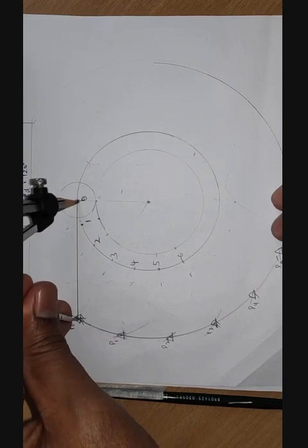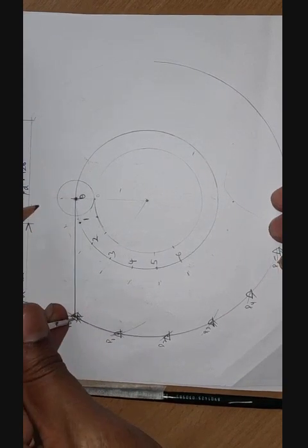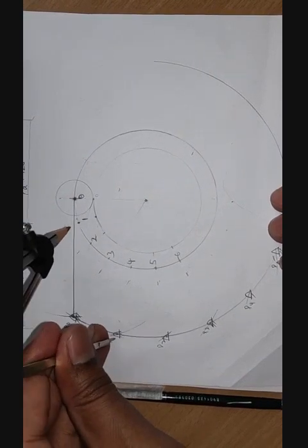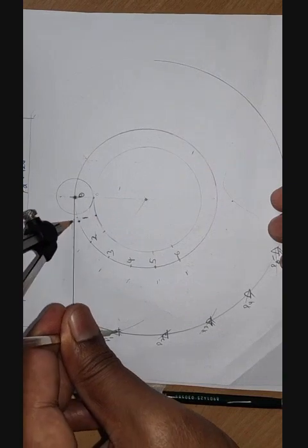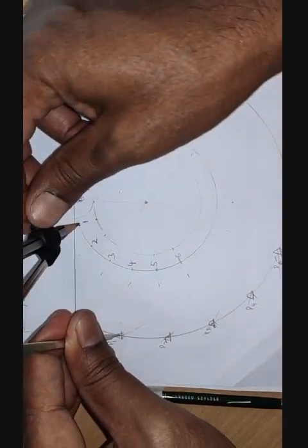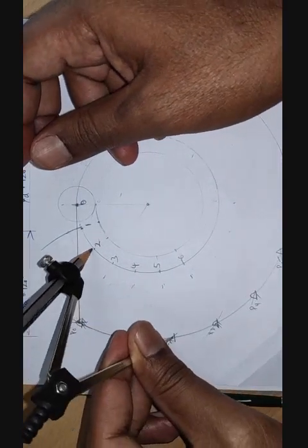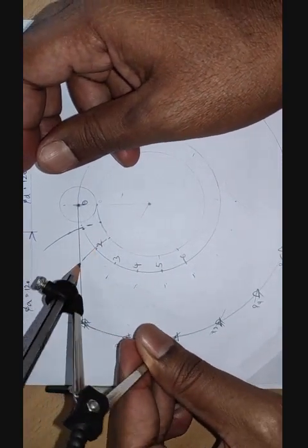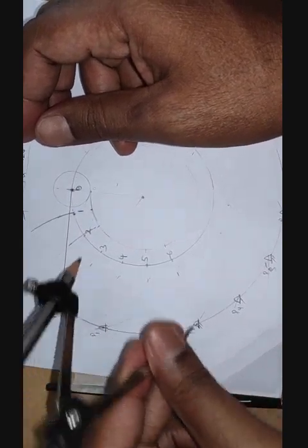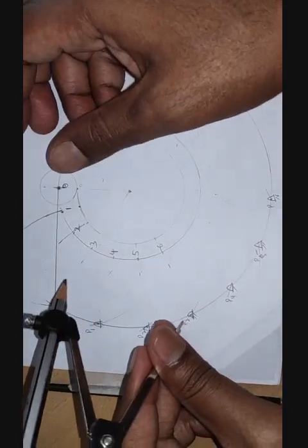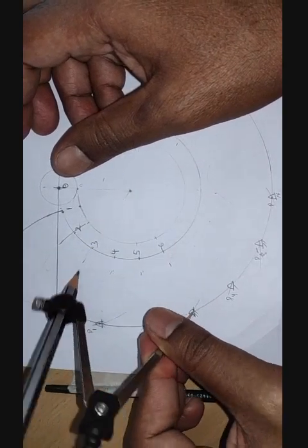So this is the length of the oscillating lever from here, and as the cam rotates by 20 degrees, the new position will be at P1. So the path of this would be through this. So it would actually move like this. From P2 it would move like this. Of course, you can see there is some small error in trying to do this because of the small mistakes that we make in drawing. So from P3 it would move like this.